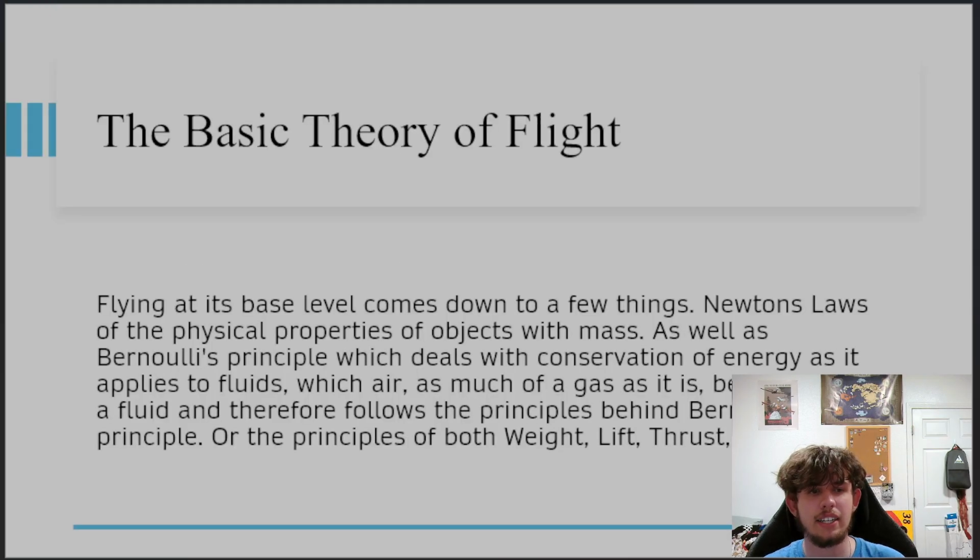Like I said, flying is a very complex thing. At base level, it breaks down to the principles of weight, lift, thrust, and drag. They all act in opposition to one another. Weight opposes lift, thrust opposes drag. Thrust helps generate lift, and while weight doesn't necessarily help generate drag, it helps bring back an airplane. So weight and drag act against the aircraft, lift and thrust act with the aircraft, and these four forces are what allow us to have the amazing experience of flight.